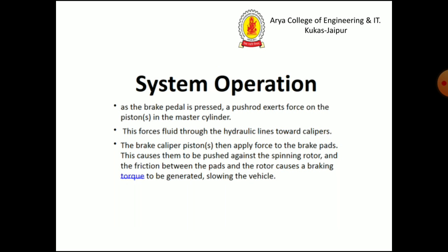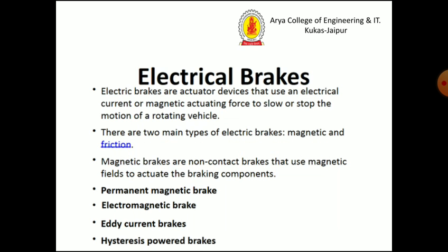The system operates as the brake pedal is pressed. A push rod exerts force on the pistons in the master cylinder. This forces fluid through the hydraulic lines towards the caliper. The brake caliper pistons then apply force to the brake pads. This causes them to be pushed against the spinning rotor, and the friction between the pad and the rotor causes braking torque to be generated, slowing the vehicle.